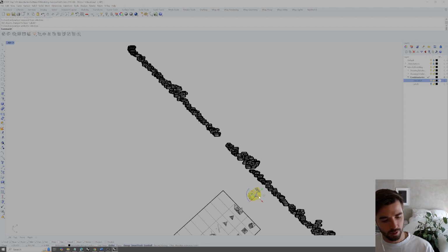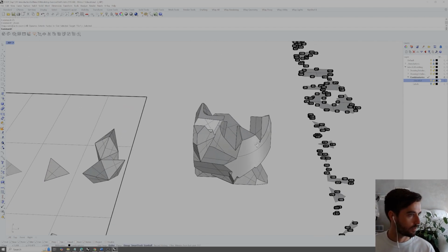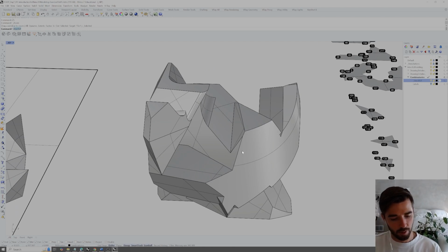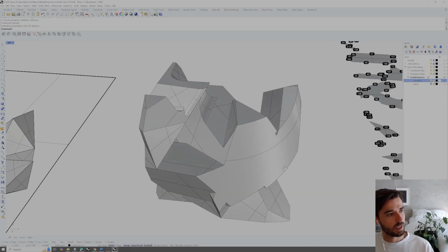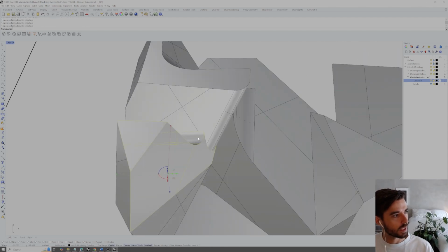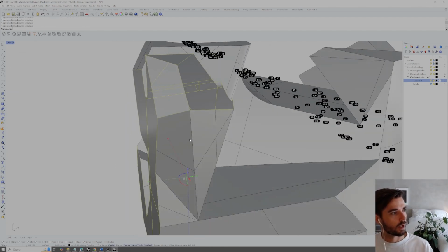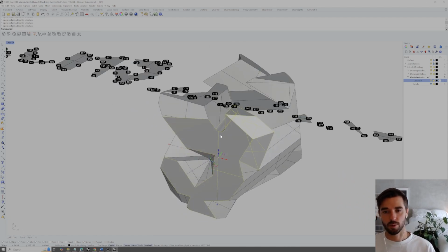But the other thing that you can do, which I'll just show here, hopefully fairly quickly, which I mentioned as well before, but you can go ahead and explode all of these surfaces, and then you can go back into the exploded geometries and start combining certain elements that you think can unwrap without distortion or without overlap.